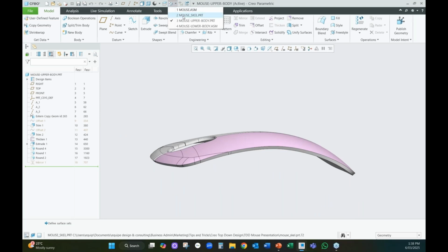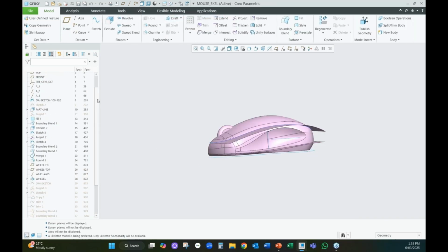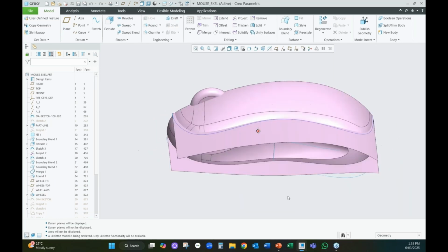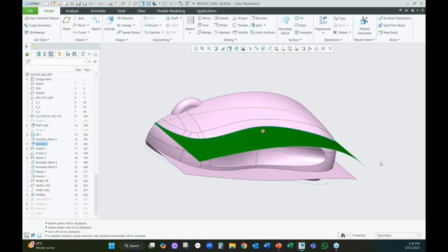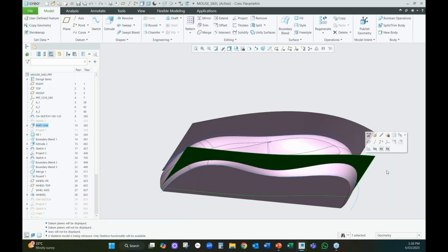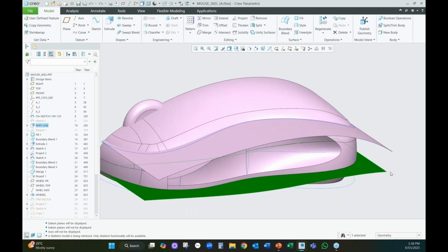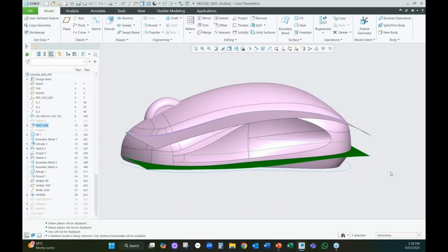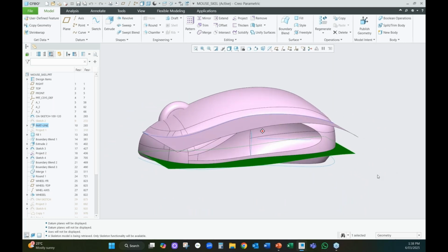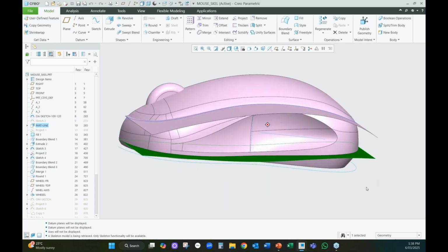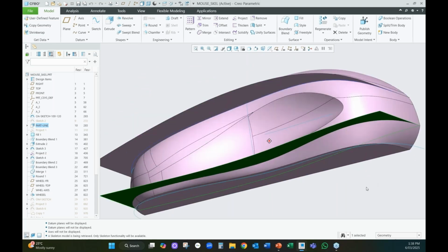So if we go back up to the skeleton, you can see that we've modelled in the complete outside shape. I've also put in some part lines, and so this is putting in at the top level any features that drive interactions between parts, and then that gives me the flexibility to define those. So part line gaps, and having them uniformly set at 1 millimetre the entire way around the product, that's done from the higher level.